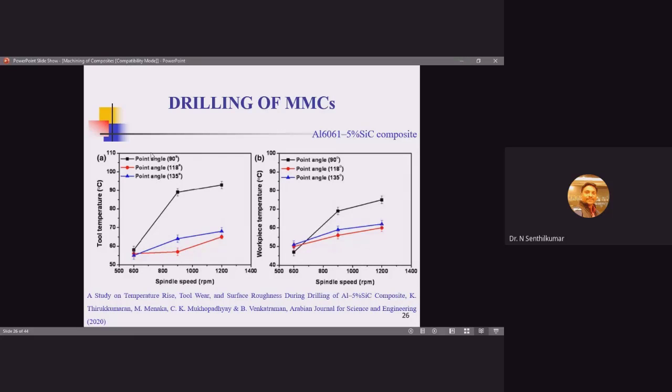There are two different ways we can measure the temperatures. One is by using thermocouples. You know the drill diameter, so apart from this, you can put 4 or 8 small holes and plant a thermocouple in them. Or you can use a non-contact type thermometer, infrared thermometers. Like the thermometer gun that we are using for the corona test to check our temperatures.